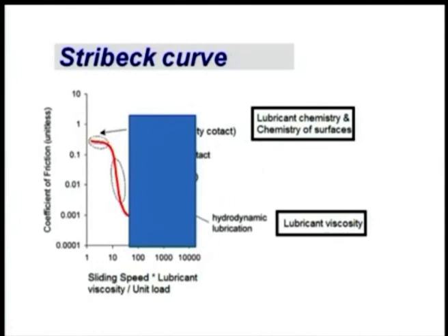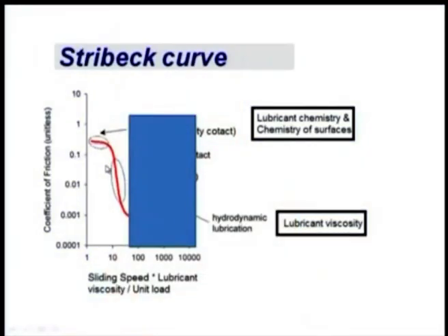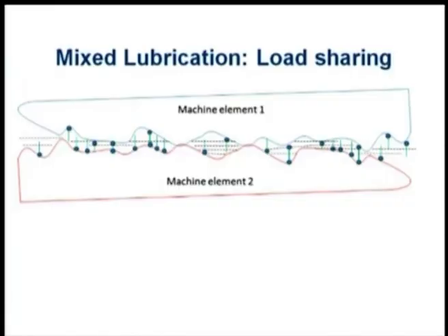But if there are restrictions, that the system cannot be operated at the right hand side, because of some lubricant restriction or supply of the lubricant, or we cannot go ahead with the liquid lubricant at all. In that situation, we need to design a system with a narrow band, and we need to keep a control on the temperature. That means, we need to provide artificial cooling, so the temperature should never go beyond a certain limit. Now, that was the Stribeck curve. It can conveniently describe what the regimes are and how one regime is differentiated from another regime.